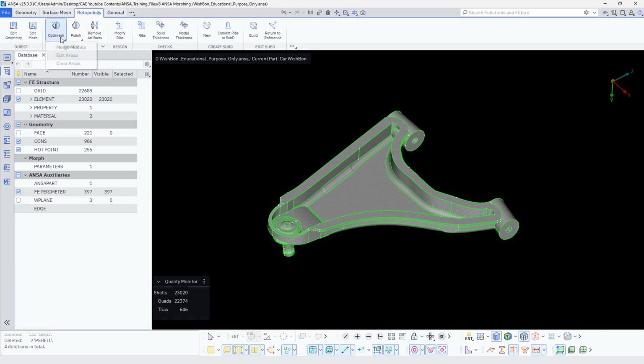This is Opti-mesh. What it does is, if we have topology results, this will help you improve that topology result mesh and the scanned models. If you use this tool on the topology results, it will try to give you the proper mesh. So we can try that.